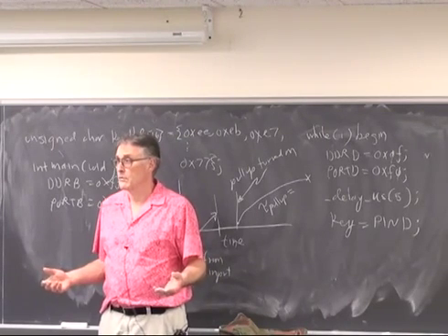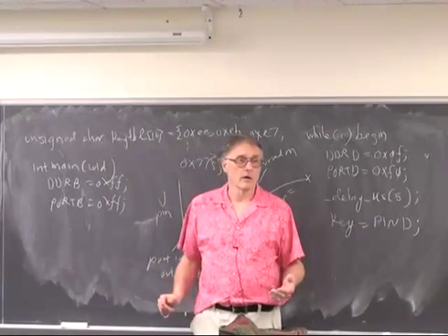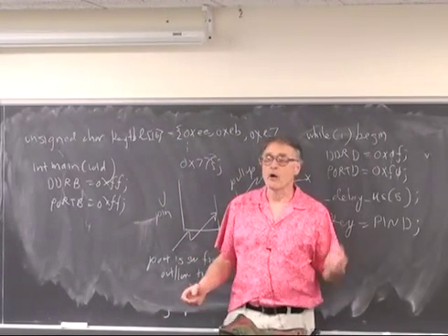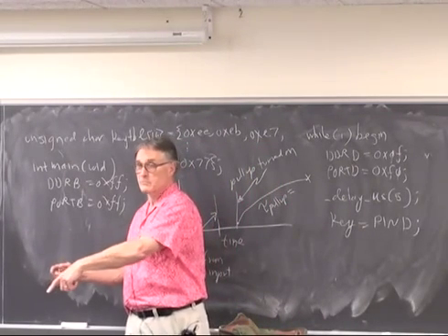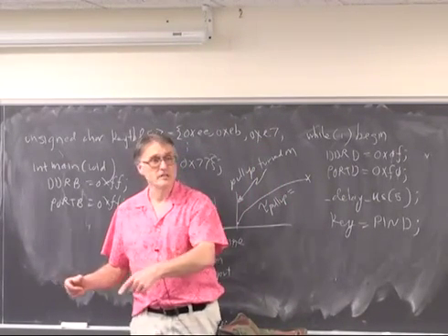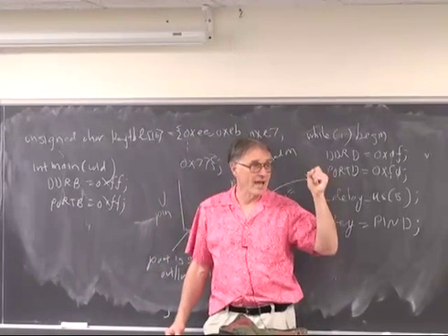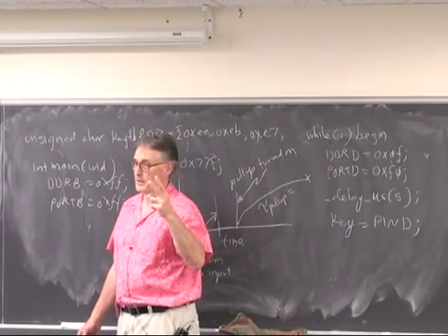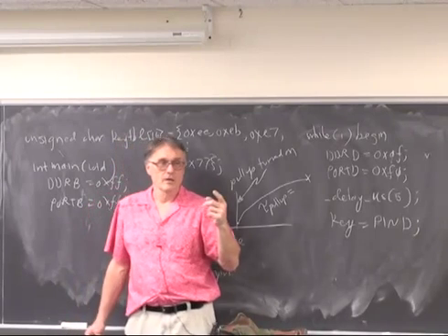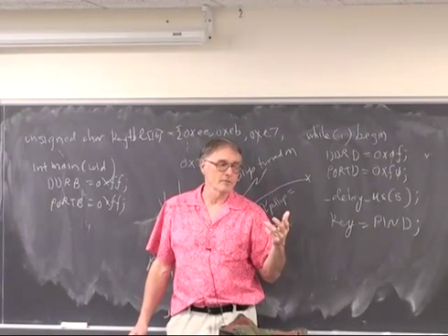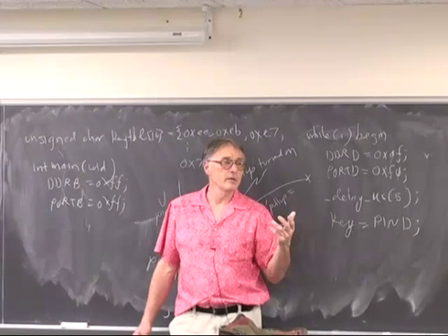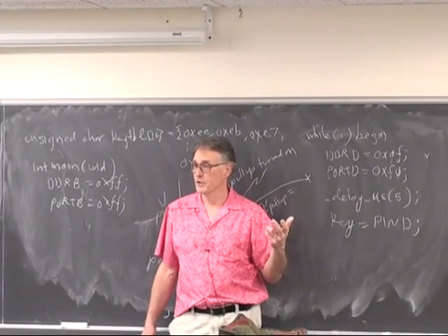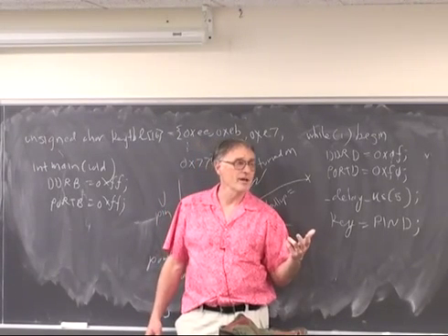Okay, yeah. You have to use an interrupt-driven system to get to know when the capture actually occurred. How are you going to detect overflow? Overflow interrupt. So you could set 2 interrupts, the capture interrupt on timer 1 and the overflow interrupt. If the capture interrupt occurs, then you know you got a capture. If the overflow interrupt occurs, now you know that the period of the square wave coming in is too long to measure with the current prescaler, and you have to modify the prescaler.